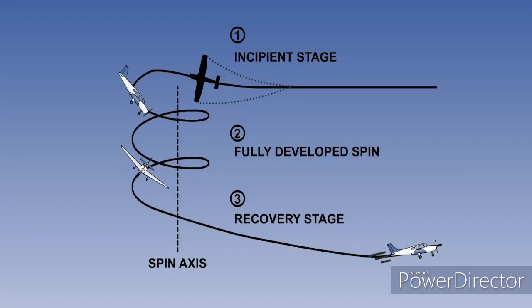As already mentioned, if at the critical angle more lift is lost from one wing than from the other, it will drop. The relative airflow will now be inclined upwards, increasing its effective angle of attack. As the aircraft rolls, the upgoing wing has a reduced angle of attack and remains less stalled than the other wing.